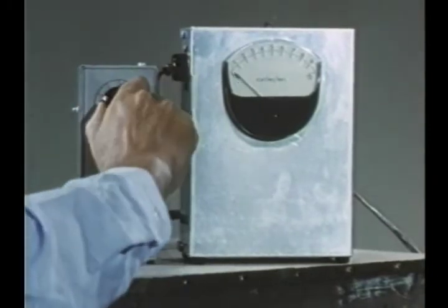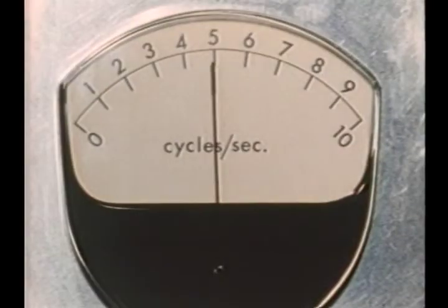We start the wave maker oscillating at 5 cycles per second. At zero airspeed, the waves are damped as they travel away from the wave maker. With the tunnel running, but below critical airspeed, we don't notice much change in wave damping. As we increase the airspeed and pass critical speed, we see the waves grow.